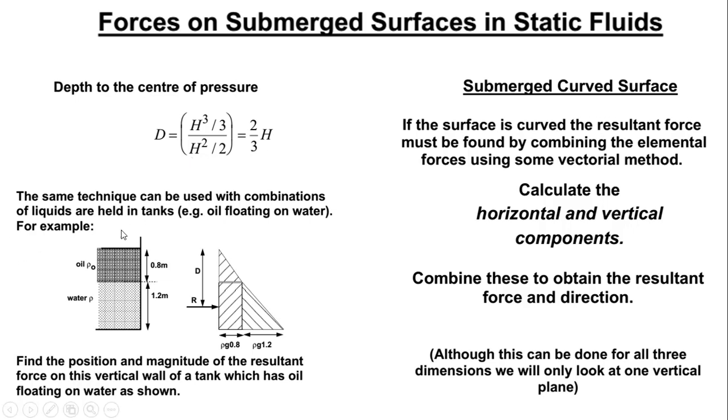Also take note of this point, that if you've got different fluids in a container, we are going to get a different approach here. This curve that you are going to get for oil is different from the curve that you are going to get for water. But you have to put in mind that despite having two different fluids, pressure will still increase with depth. So we are going to get higher pressure at the bottom of this tank, for example. Okay, so let's look at the last part, which is submerged curved surfaces. How are we going to solve problems that have curved surfaces?